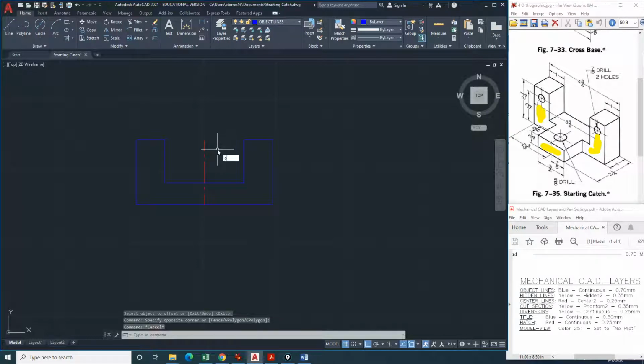And then from there, I'm going to offset that center line according to the handout, 7/8 from the center to the right. I'm going to offset it 7/8 this way. Now, could I offset this thing 7/8 this way? I could, but I don't know what these two would add up to be. Now, I don't have to calculate that. I can simply use the information on the drawing and offset this 1 3/4 from here this way. Okay. So I don't have to calculate. Students, if you're noticing that you're having to calculate a lot of different things, you're not using these drawings correctly.